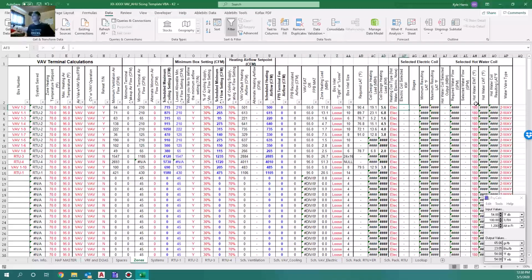But we're going to use nice round numbers at 6 kW, and you can see in column AI, the resulting leaving air temperature is 92.9 degrees. So let's say this one is 7, this one is 2, so it's 83.7, that's good. You don't want anything lower than 85 just for the sake of creature comfort. So let's say 5. Oh, this one's lower, so let's make that one 6. So this one is a 4. Where does that leave us? Ooh, that's really low, 72 degrees. Let's heat that air up to, we'll say 6 kW, 7 kW. There's 85, that's good.